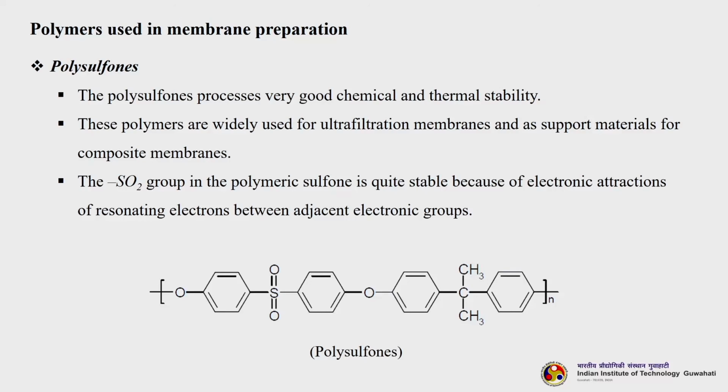So, the polysulfons possess very good chemical and thermal stability. These polymers are widely used for ultrafiltration membranes and as support materials for composite membranes. Most of the ceramic based composite membranes use polysulfons or polyether sulfon to impart the top or skin layer on the surface of the ceramic membranes, whereas the ceramic membrane is used as the support.